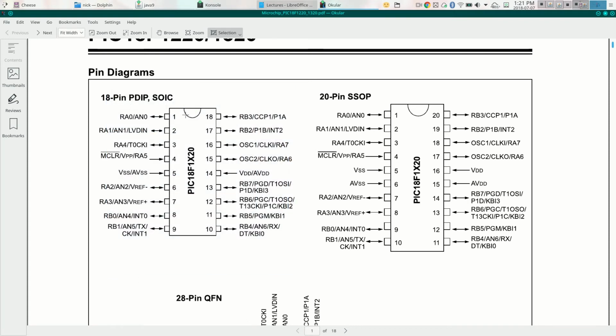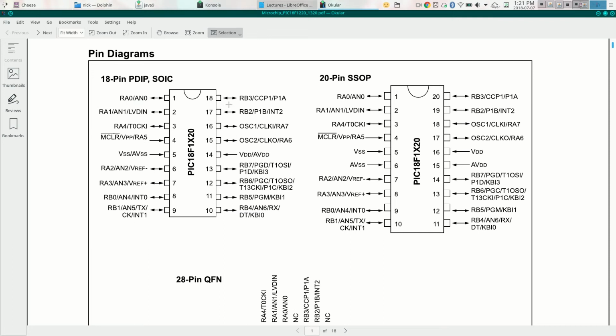And the first thing you'll notice is that this looks a little different from, say, a 74LS04, where our inputs were labeled A1 or X2. There are lots of labels on these pins. So VSS is ground, pin 5 is ground, pin 14 VDD, that's power. So ground and power go on 5 and 14, that's not too hard.